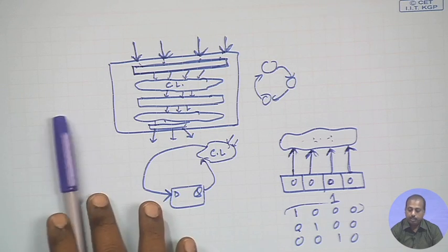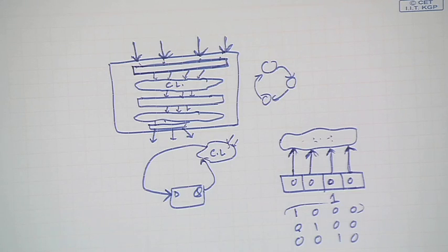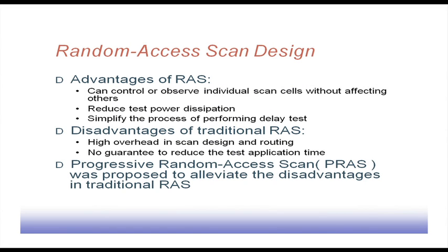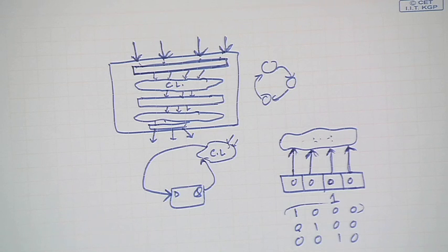And as and when they make the transition, it will consume power, and we know that for CMOS circuits this power is consumed only when its output changes. The dynamic power is consumed only when its output changes. So, if the input does not change, output does not change. If the input is changing, then there is very high chance that the output will also change for different gates in the logic. So, if I am doing a serial scan, then at every shift I am consuming some power, because that input will go to the combinational logic.